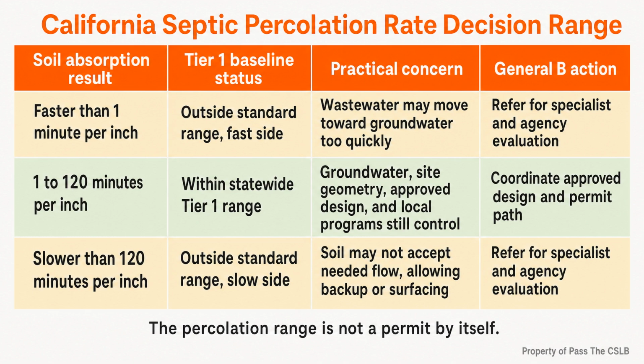The proposed building footprint fits, but the contractor has not confirmed whether the existing septic system can support the added load or whether the dispersal area can be expanded. If the contractor finalizes the foundation layout first, the later wastewater approval may force a redesign, a relocation, or a more expensive treatment approach. The mistake is not failing to perform septic engineering. The mistake is treating septic approval as a late plumbing detail.